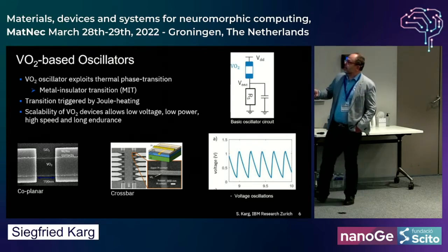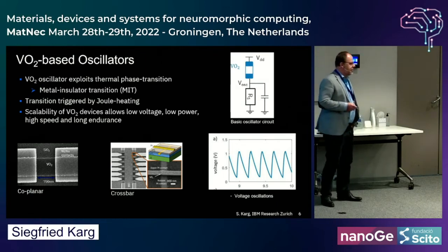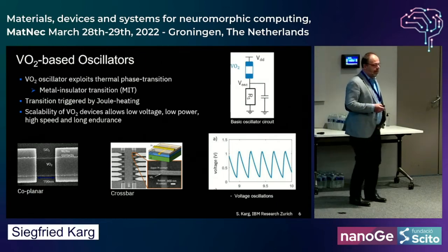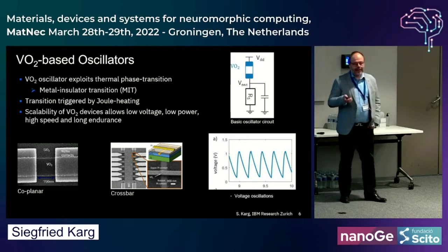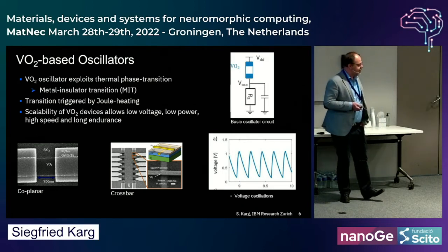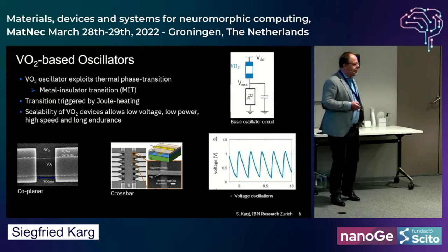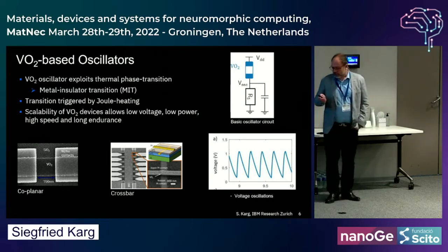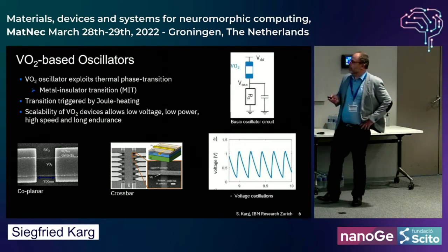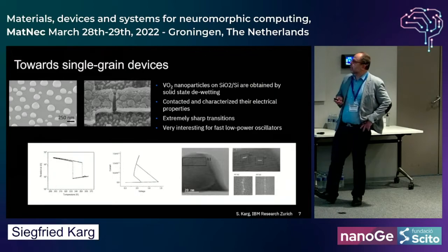We will add another capacitor, which is not strictly necessary, but of course in practice there always will be some parasitic capacitance, and we'd rather put in a capacitance that we know, then we can control it. It also has practical reasons for our circuitry because we have limited time resolution.